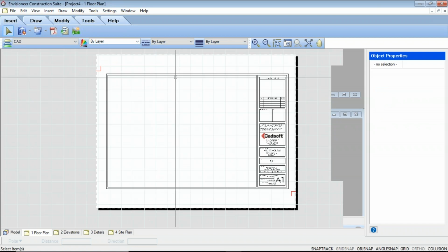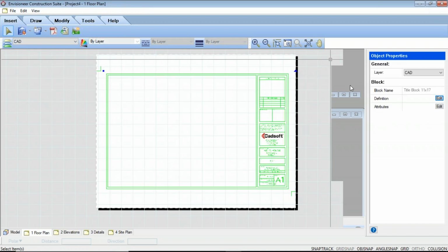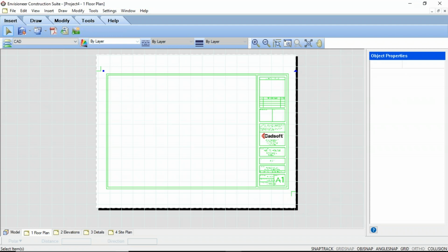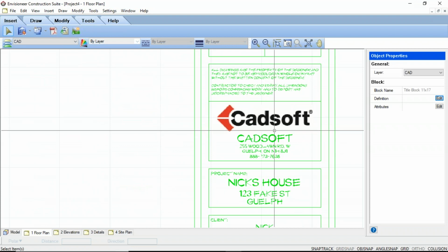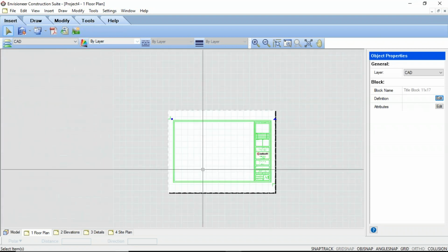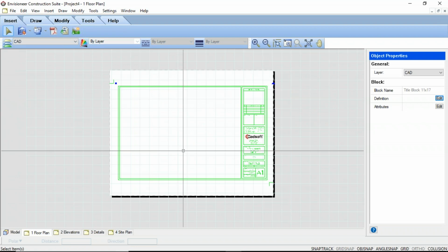now this sheet is going to be using that title block that I believe I inserted was an 11 by 17. So now I will go through and make the same changes that I did before, adjusting the logo, adjusting the company information, and then save this as my template. And now this template is going to be 11 by 17. The sheet sizes are still going to be a 1/4 inch scale, though, unless you want to change that to be 1/8 of an inch. But again, my suggestion is leave it as a 1/4 inch. It's the same that is in model, just change your Smart View as you're importing it.